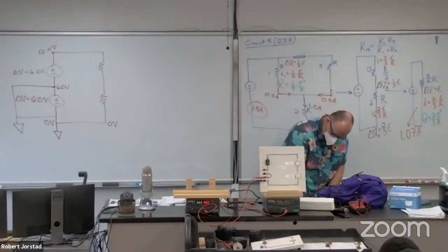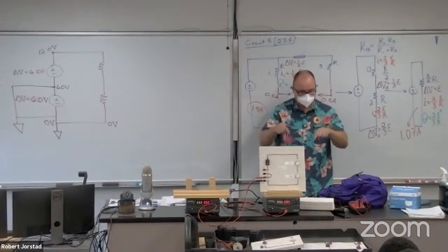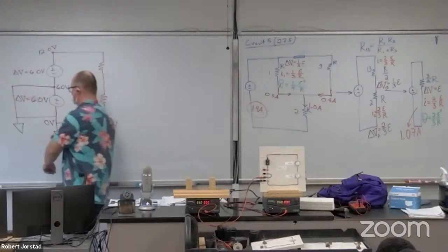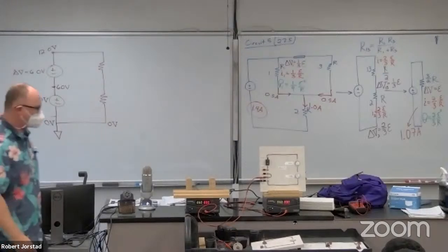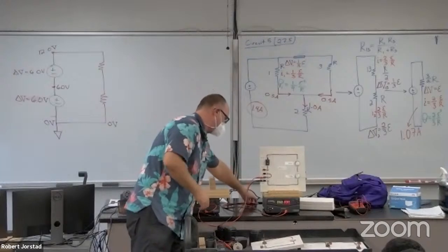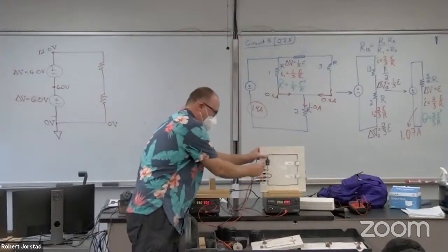When I do that and plug it in, I'm going to operate it in a safe way in this case, right? What I'm doing is I'm disconnecting this circuit from ground, this one power supply. The entire circuit is still grounded, right? And so I'm not worried about electrocuting myself because there's a ground reference right here. I know that one of these power supplies is grounded, and now this one is called floating. That breaks this connection to ground. This is now a safe circuit, all right? So you don't want to mess around with that unless you know what you're doing. So now in this case, I can plug in this other power supply without worrying about a spurious ground loop.